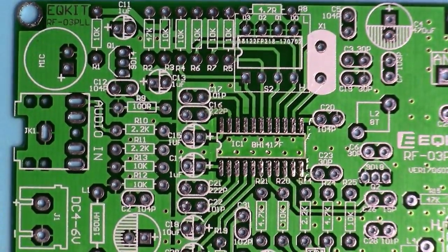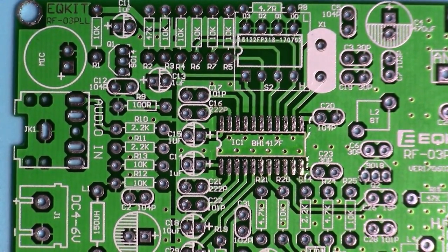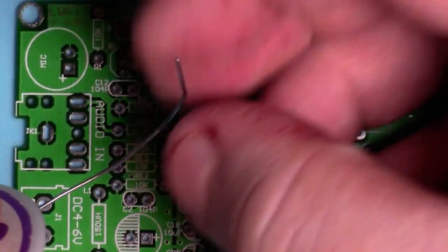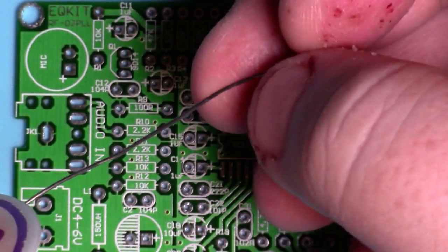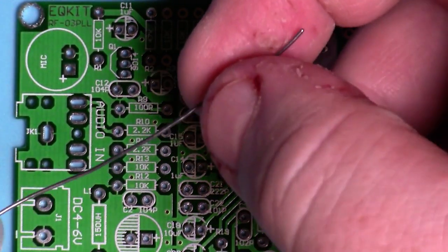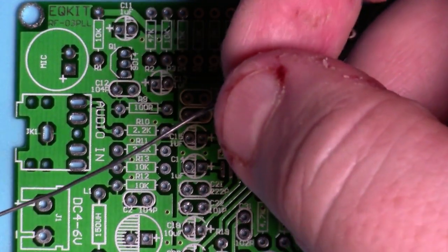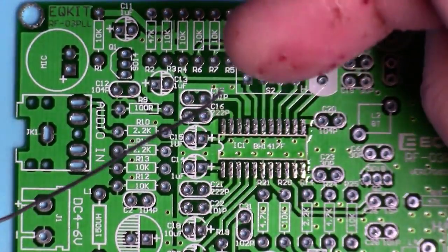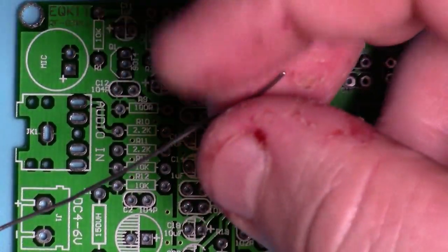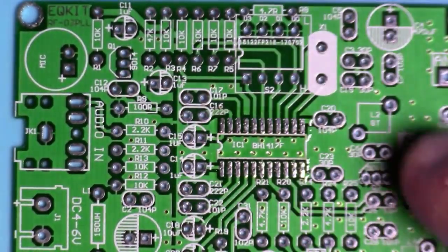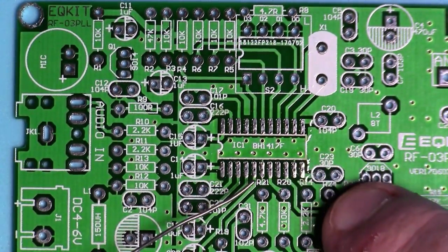So, a little review. What do we remember about soldering? Remember that this is solder, and this solder is a hollow tube, and inside of it is flux. Because solder wants to follow heat, and flux is what enables it to follow the heat. Now normally for all the rest of the components, just the flux that is in the solder is going to be plenty. However, with our surface mount device, we're actually going to use the flux to guide the solder.